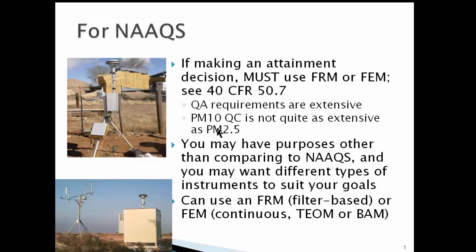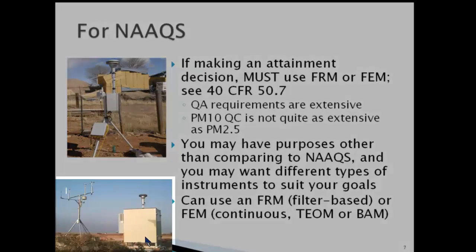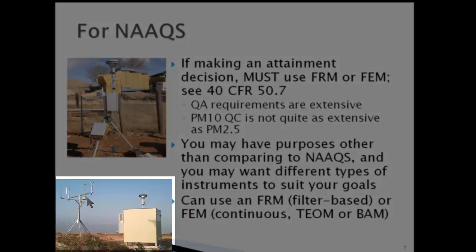So QC requirements for PM2.5 are a lot more strict than PM10. This is a picture of an FEM device monitoring particulate matter on the Navajo Nation, and you can see they're just barely at the limit of 33 feet from that temporary building there. And this is a picture of a TOM and a MET station.